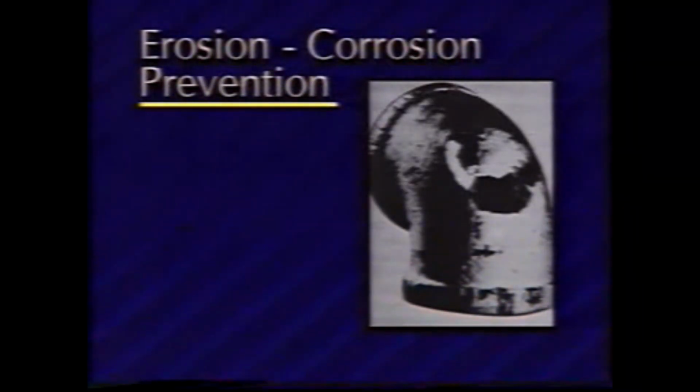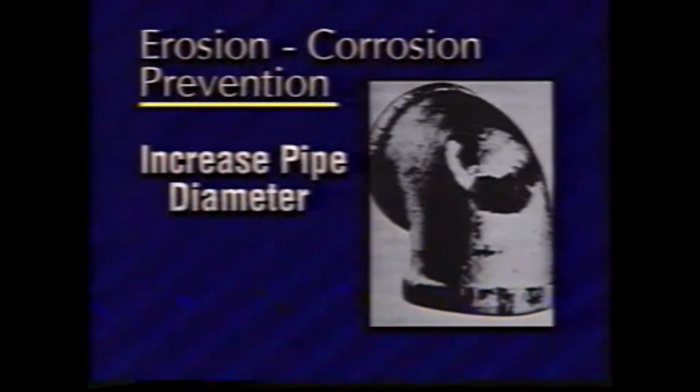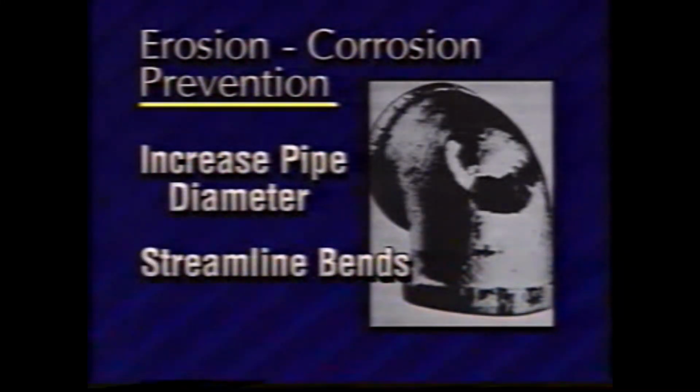In piping systems, the milder forms of erosion corrosion, as well as impingement erosion, can be reduced by increasing the diameter of the pipe. This decreases the velocity and turbulence. Frequently, small reductions in velocity can greatly reduce the rate of metal removal. The streamlining of bends is also useful in minimizing the effects of impingement. If possible, inlet pipes should not be directed onto the vessel walls. Flared tubing can be used to reduce problems at the inlet tubes in a tube bundle.